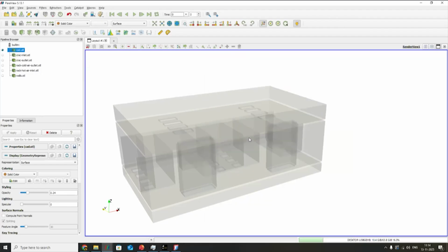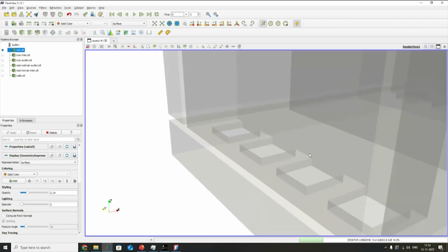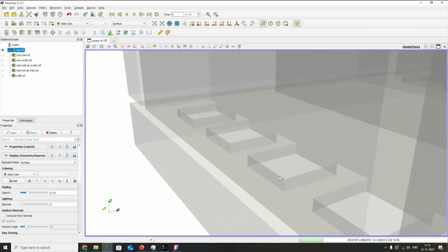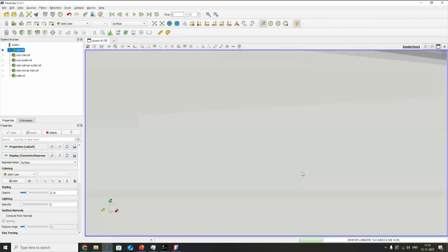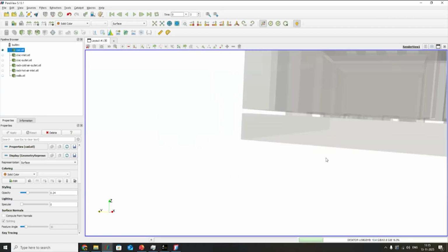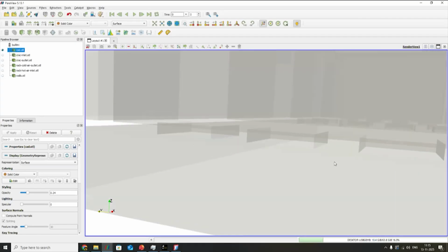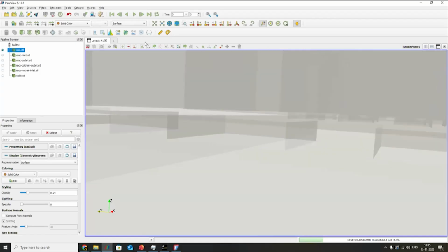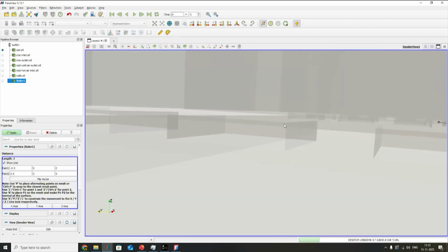So why am I choosing this? So this is the meshing strategy. So here I can see I have this small face here, which is the smallest face in my geometry. So I need to measure its dimensions. And if I try to measure it here, how can I do it? I can use this create ruler option. I can click on a point here, and I can again press P on my keyboard to create another point.